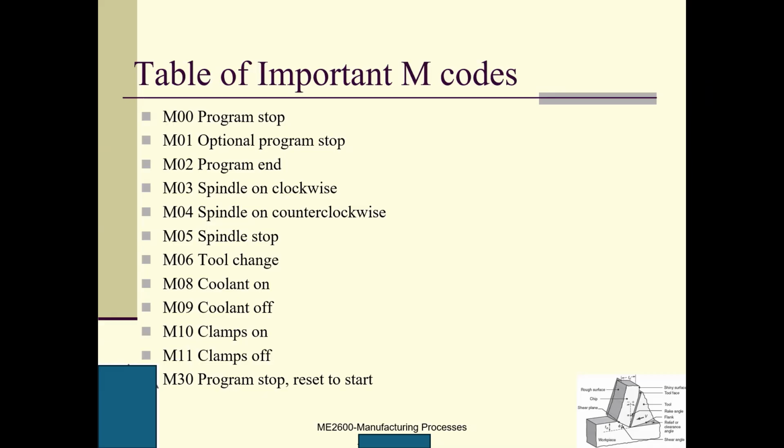If you see M08, the coolant will be turned on. M09, coolant off. M10, clamps on for the workpiece. M11, clamps off. M30, program stop.